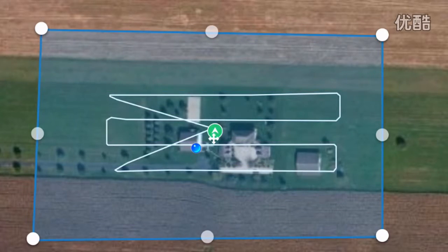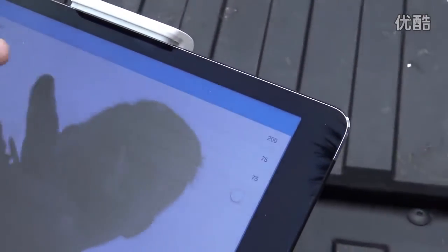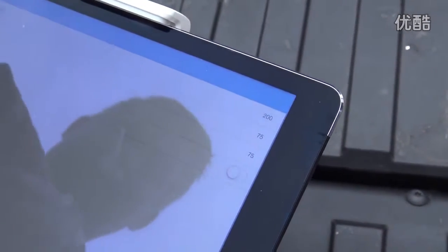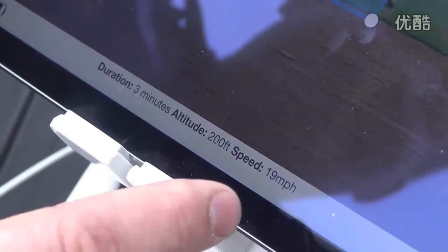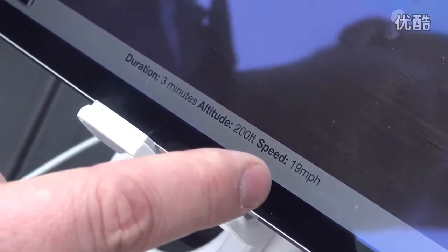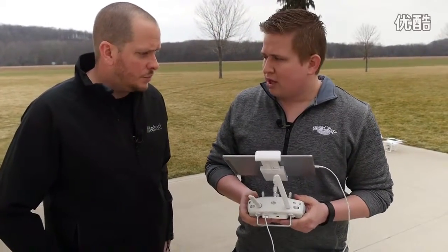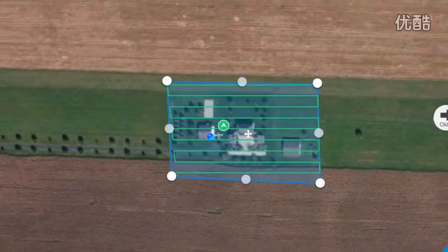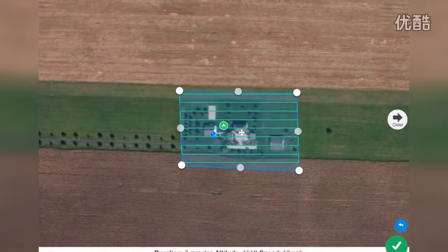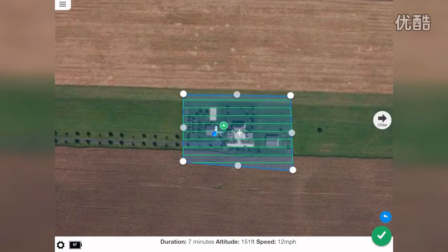Yeah, that's something that I didn't know yesterday when I was first trying it, is that that's all stuff you can edit. So you can edit the altitude that you want to have it run at while it's doing its grid. One thing that I found is that the lower it is, the more resolution you're going to get, but the higher it is, the easier it is for the software to stitch, because it has more reference points for how to actually stitch it together. And obviously, the more information it has, the more it can do with it. Correct, yeah. And so you can fight that by increasing the overlap. I think for this one, I'm running the overlap at like 75–80%. Okay. And that's a lot of overlap, but it's how you get the most accurate data.